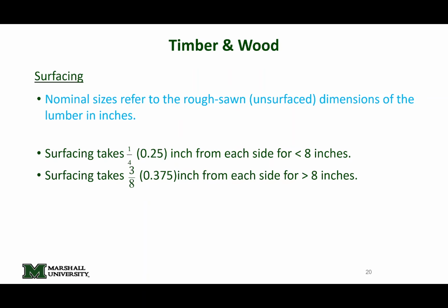Now, at the end of the day, you have your rough cut lumber, you dry it, and then you will take that dried, rough-cut lumber and surface it to get the final dimensions. I've got here in my hand a section of a 2x4. This is not 2 inches by 4 inches, okay? This is 1.5 by 3.5. What's happening is an actual 2x4 was dried, probably for a species like this, in a kiln.